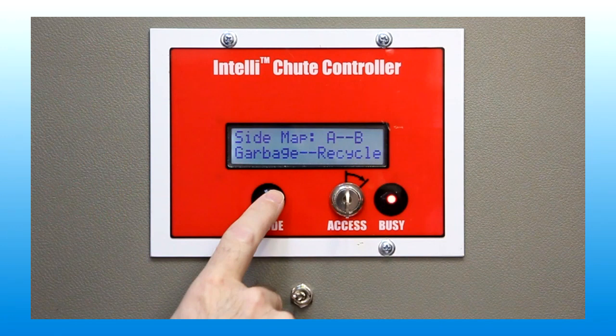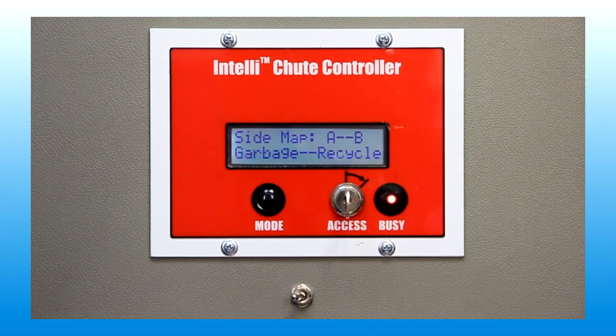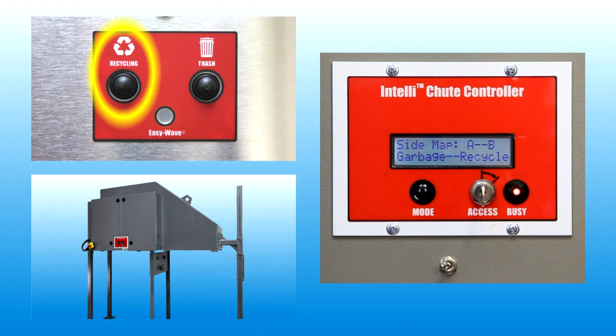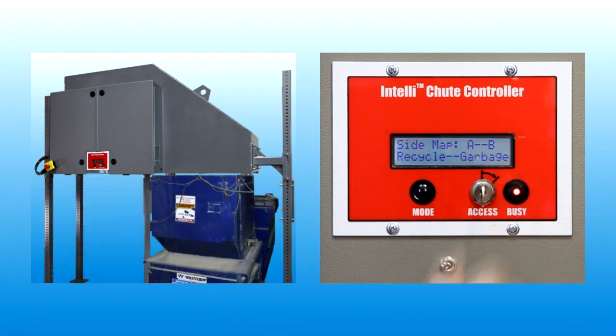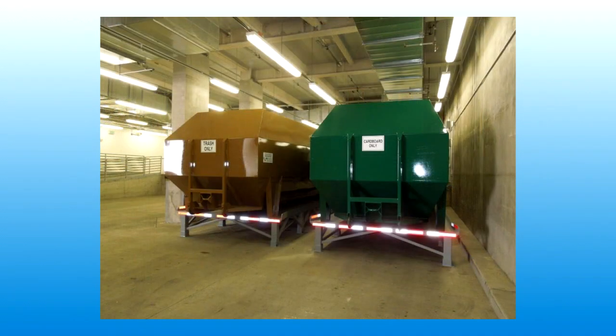The Side Map parameter determines how the BiSorter sets up the diverter plate position in response to intake door push-button selection switches. By default, when the trash button is selected, the diverter plate moves to the vertical position and trash is sent to side A containers. When the recycle button is selected, recycled material is sent to side B containers. Select the alternative option to switch this association. Now recycle is sent to side A and garbage is sent to side B. This feature determines the position of waste containers and can be used to optimize the placement of large dumpsters associated with trash compactors within the floor plan of a building.